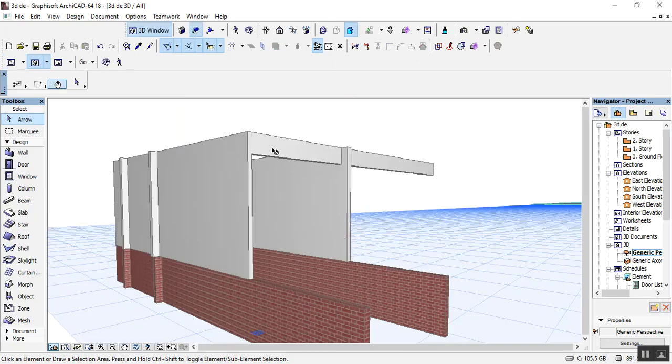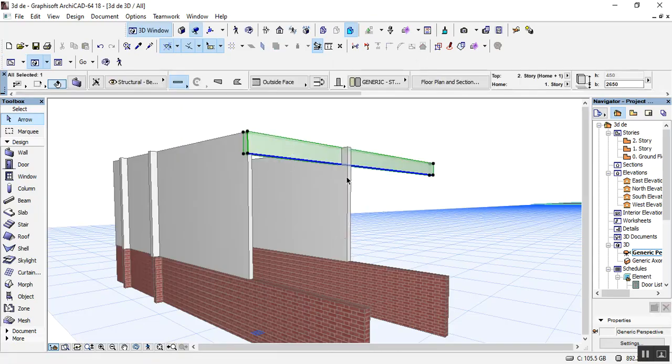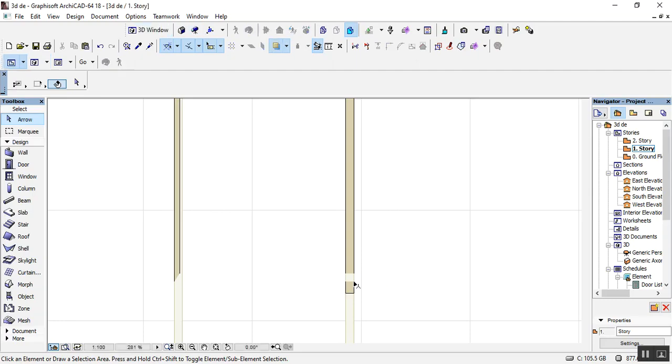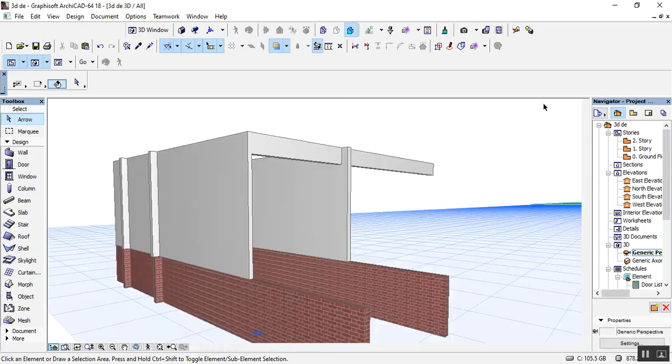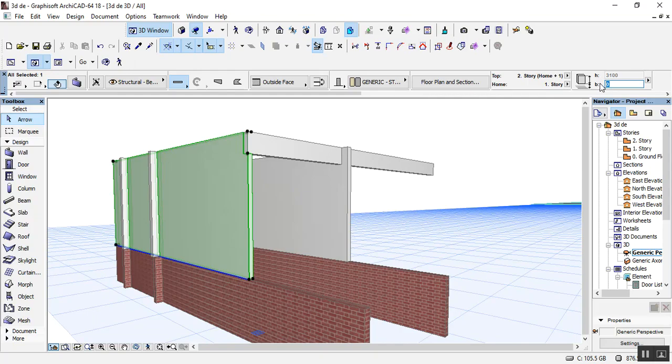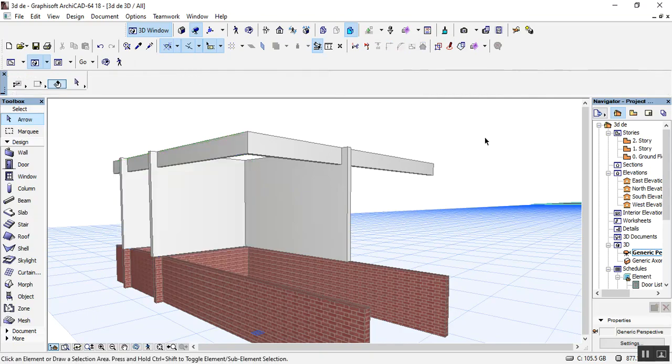You can see this is what we just put. For you to edit this wall on your 3D, you need to come down to your 3D and send this back to 0, or you can't edit this wall from your normal floor because you won't be seeing it. It's an invisible wall. You can see it's always invisible because it's not sharing the same height with this. So another way to create this wall is to click this. You come down to this button, you input what you want to put. 2650, and that is all.